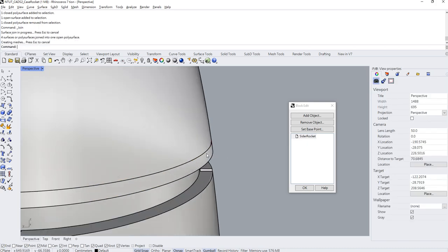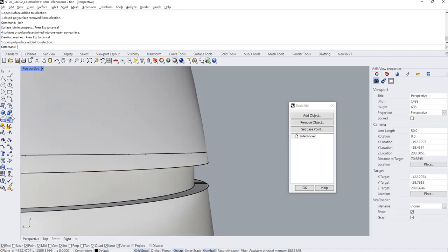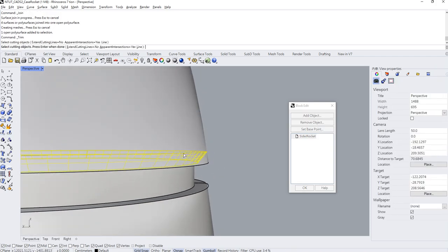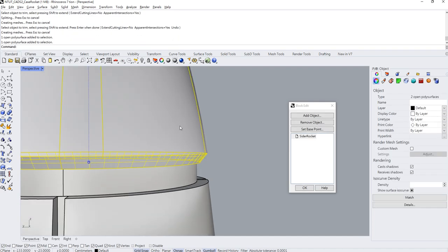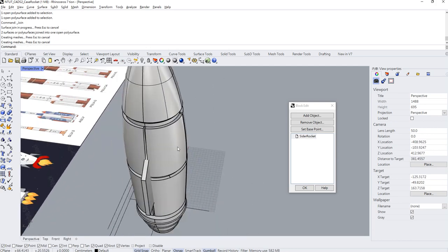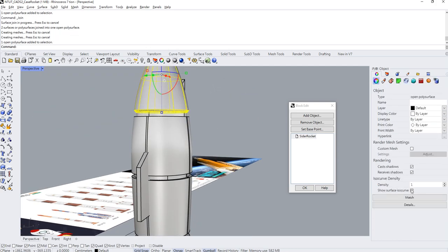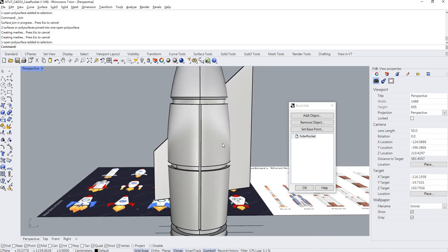Alright, anyway, so for now, let's use this inner surface to trim the outer part. So let's use trim again, choosing the surface, press enter. So now we have Ctrl J for join. For all the things here, that's pretty much the same. So I think it will happen again, but let's just ignore that part, alright?